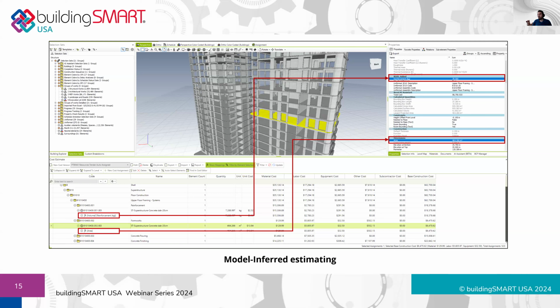But on the other hand, on a regular high-rise residential building, it is probably not wise to model to the latest detailed reinforcement. You could simply use a model-informed approach, where you rely upon the concrete element, which will contain in reality this reinforcement, and simply populate an additional property, which will be reinforcement density for that specific element.